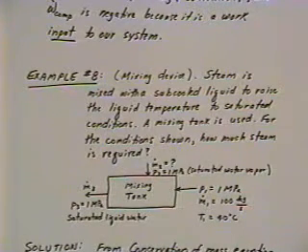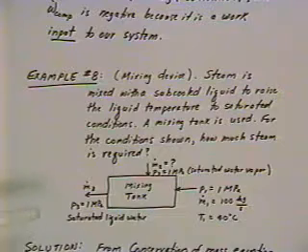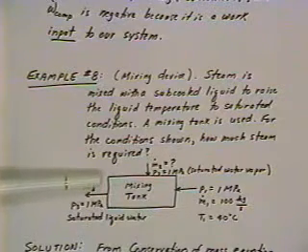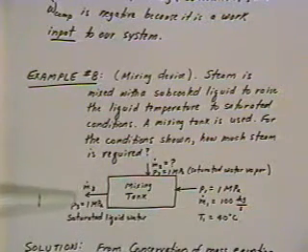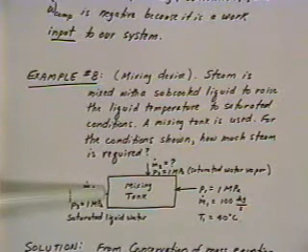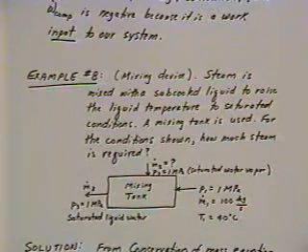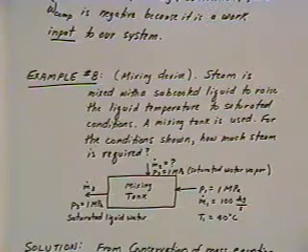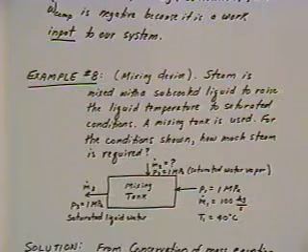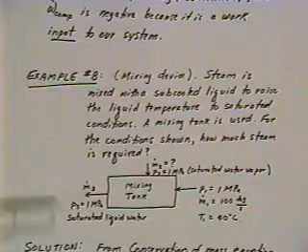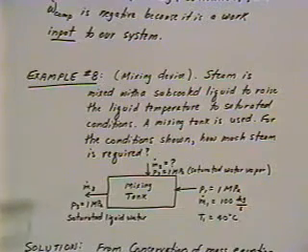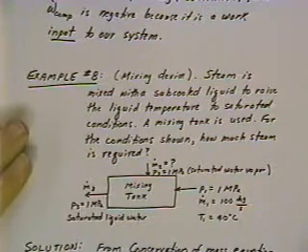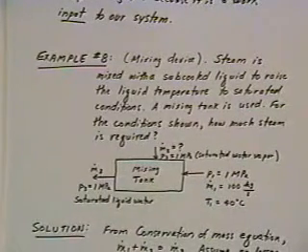And so this is a common process that's used in a power plant to raise the energy of the water entering the boiler. You do this generally by pulling steam out during the process and mixing this generally low pressure, low energy steam with liquid water in order to raise the energy level of the water entering the boiler. Okay, so this is our setup then.